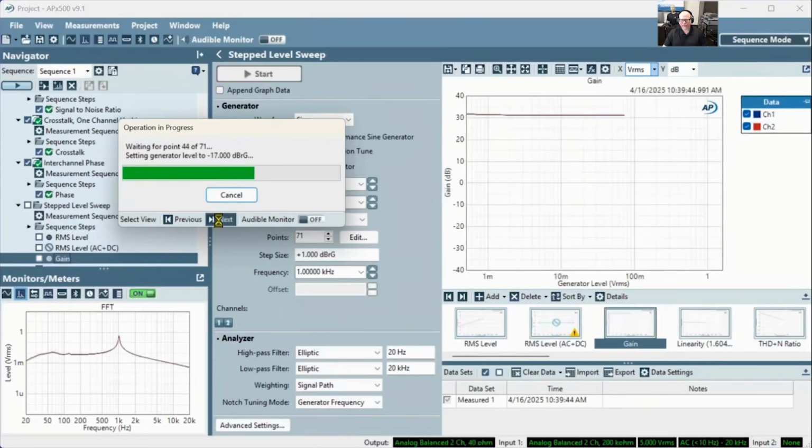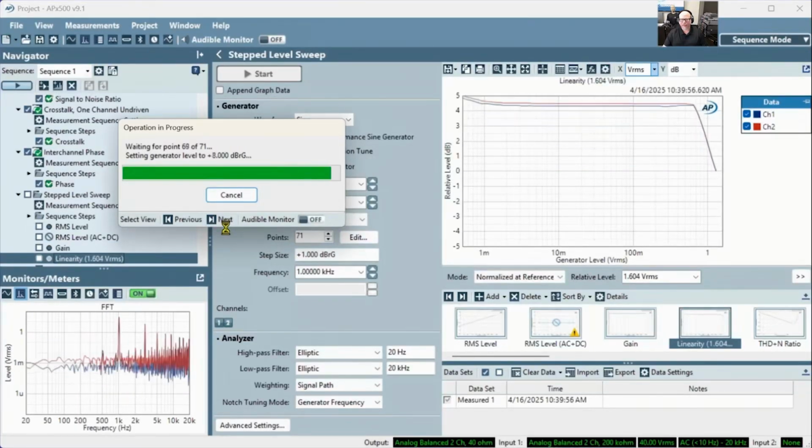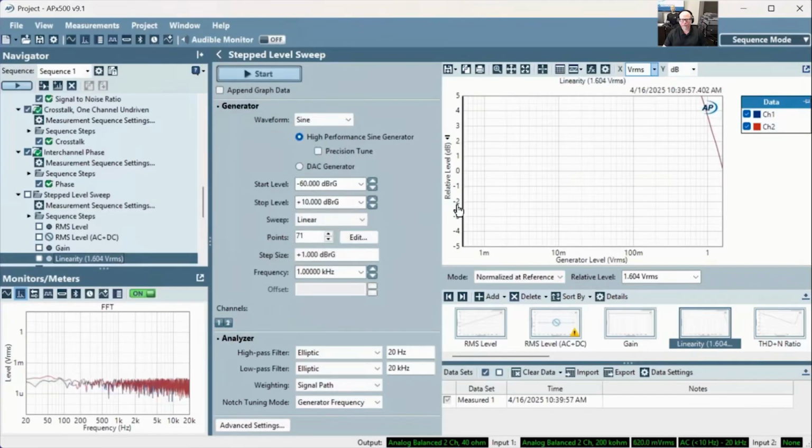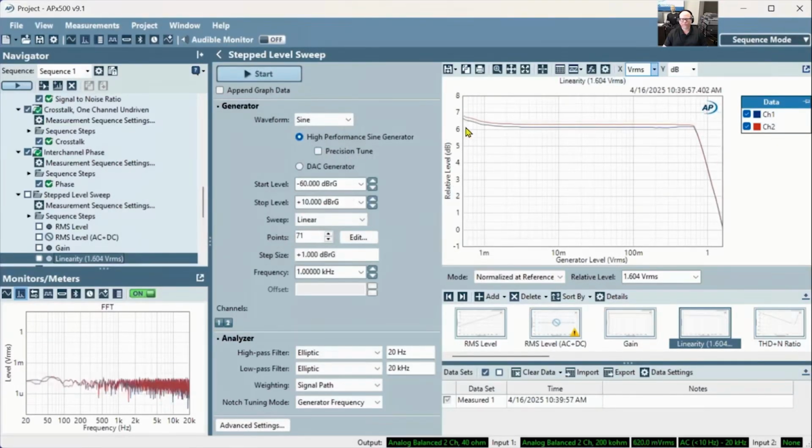Here's our gain. So we should see ideally constant gain across the amplitude regime. You might know that term as amplitude linearity. Let's take a look at this result for a moment. Here we can see that at very low levels, the amplitude linearity is off, and that's because at very low levels, regardless of the signal we put in, we're getting a lot of noise out.